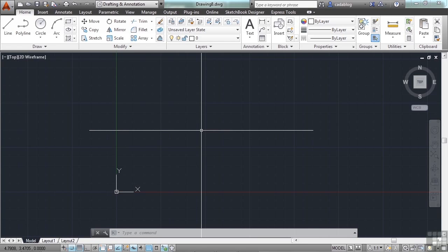You can set these increments to whatever value you need it to be. If you need to draw objects at incremental units or factors thereof, then snapping is a great way to go. It helps you to draw in these increments every time without doubt and without tedious data entry. The snap technique is not very useful though when you are zoomed way out or you're too far away, because the farther you're zoomed out, the more difficult it will be to see where you're snapping to. So it's a relative thing. You'll have to pay close attention to your coordinates in this case.